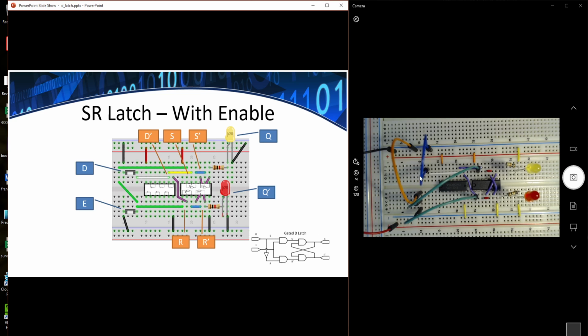All right, so looking over here at the circuit, we have that set up. We have the 74LS00 or the quad NAND gates that we've been using for the latch. And we have the outputs coming in here to the yellow for set and the red for reset, and we have the outputs crossing back over to the inputs of the respective gates.